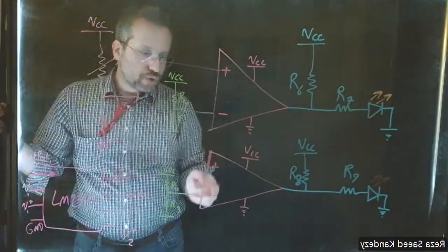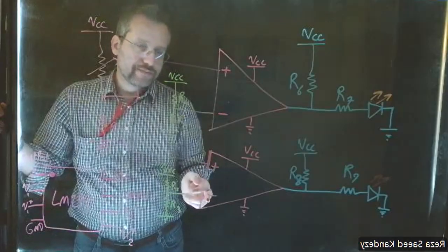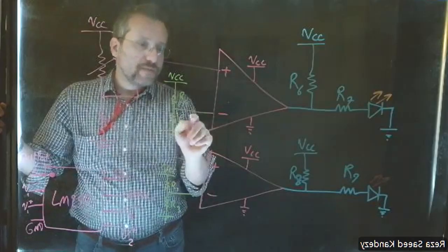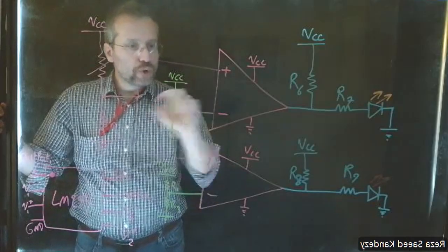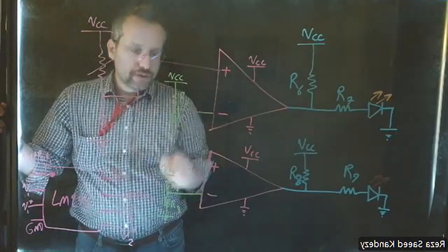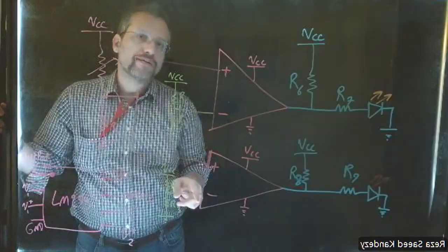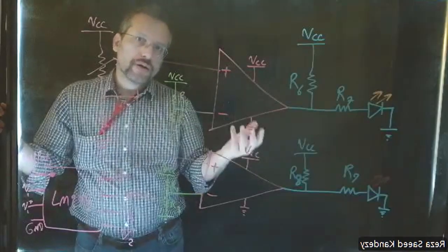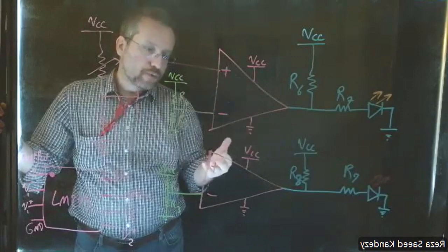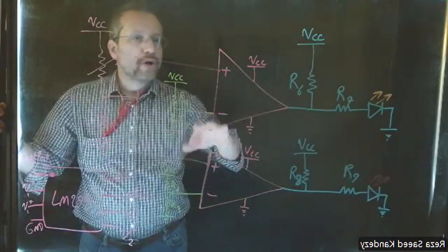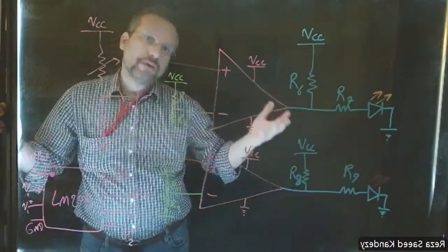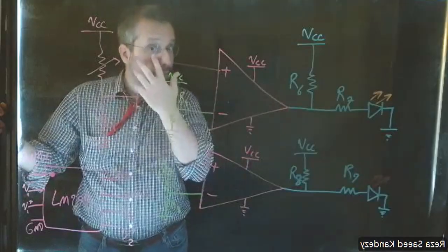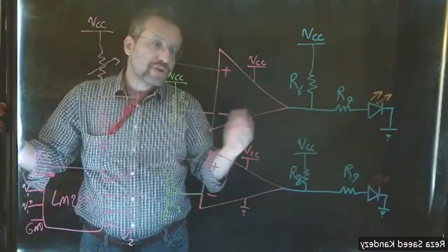Now, we have to have two sets of reference, and we are going to again use voltage division to set the two references. When we want to use the op-amp to analyze how much the temperature increased in your environment, you need to set a threshold.